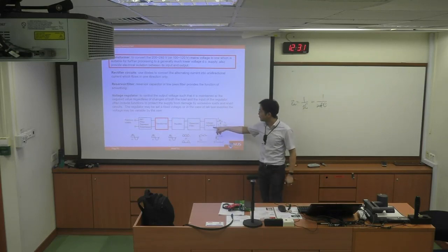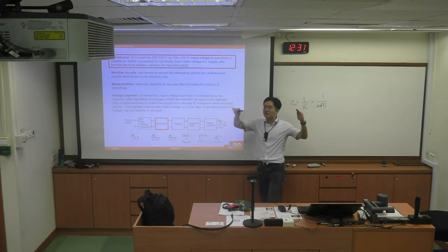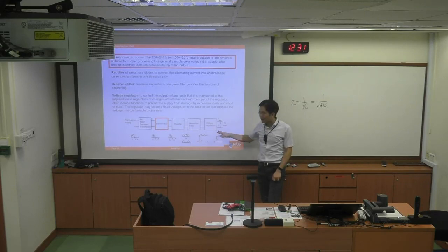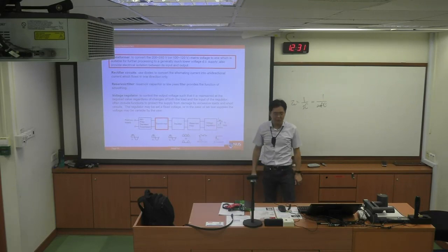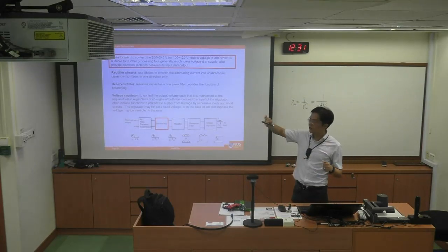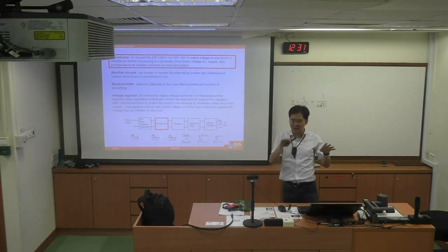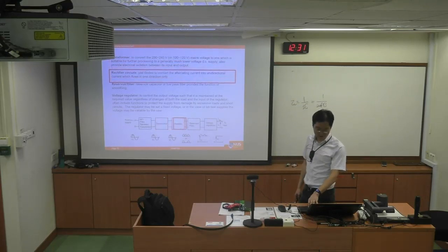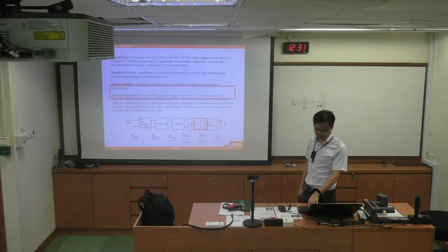So then you need a voltage regulator to change that rippling signal into a constant DC. Basically, today what we'll be learning is how to do the voltage regulation as well as line regulation. We'll be talking about the variance under load condition or the ripple in the input, how you make it a constant DC voltage. Right? Rectifier, reservoir, as well as the voltage regulator.